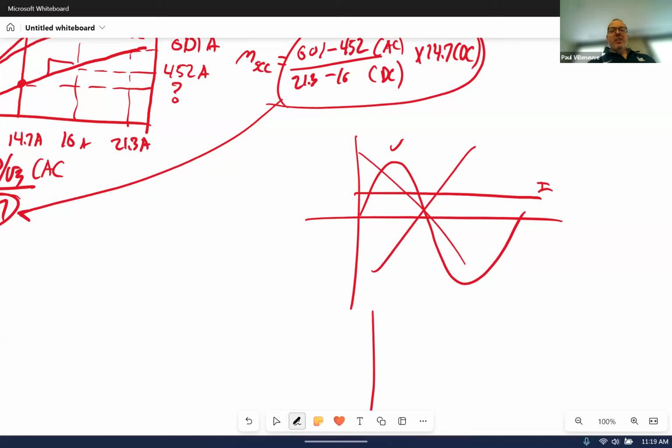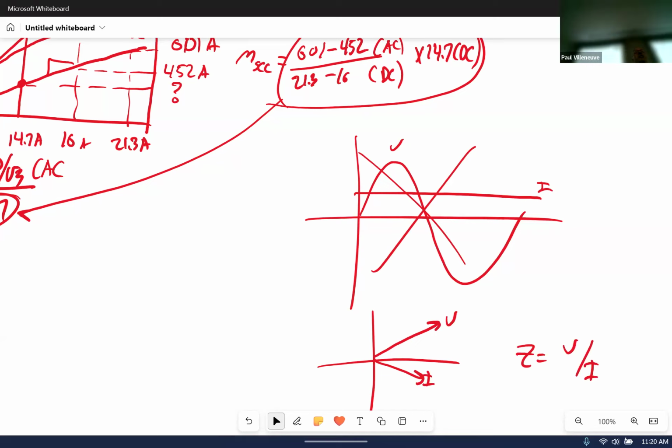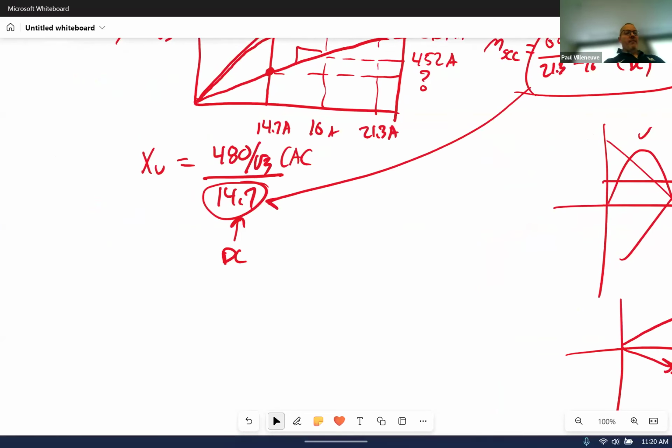What we do is we divide our phasor voltage by our phasor current, and then that gives us the value of Z. So that does work when we do that. But these are both phasors. And a phasor is a rotating vector, or it's a sine wave. So both the voltage and the current have to be sinusoidal. Okay?